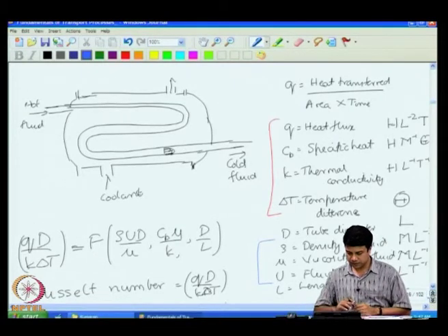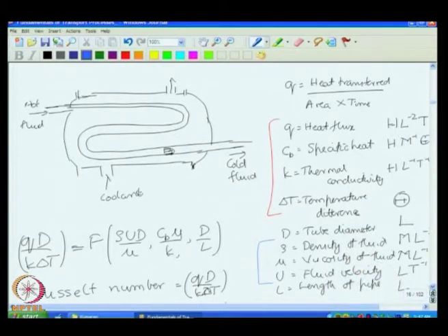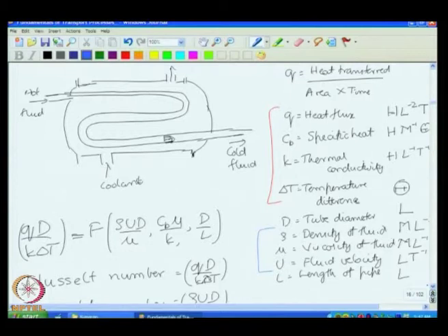When we did the dimensional analysis, we had separated out the quantities into thermal and mechanical quantities. We had said that there is no interconversion of energy from thermal to mechanical energy. Strictly speaking, I had 9 variables and 4 dimensions, so I should have been able to get 5 dimensionless groups in this problem.